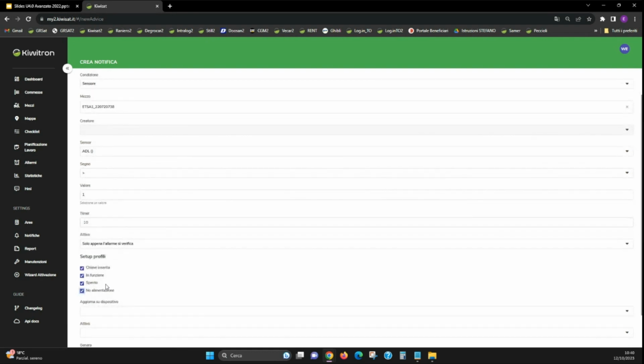Is it okay to activate them all? Attention, because with no power, especially no power, the GPS activates randomly to preserve the battery. For example, every hour, it goes from one fix, because it was off, to a fix. When this happens, the position could be more imprecise, because the GPS position is a mathematical calculation from several satellites. So, if a satellite makes a slight mistake, that is our first indicative position. However, as soon as the other satellites are connected, immediately after that, the mathematical calculation is re-elaborated, based on the other satellites, and we have a more precise position.